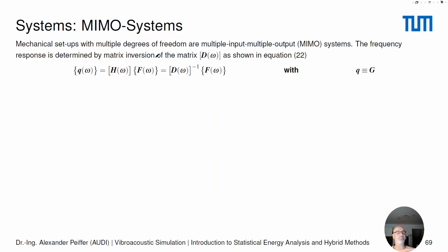In the derivation that I've shown before, the multiple mass and spring system in the configuration of session 3, I guess, you see clearly that this transfer matrix corresponds to the inverse of the stiffness matrix, because it was on the other side in the equations before. Here, specifically equation 22.